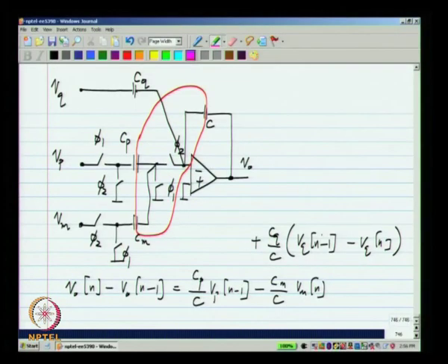Now, in this course we will not deal with the switch capacitor filters in such great detail. So, what I will do is show you a switch capacitor topology for a second order filter, which turns out to be slightly more efficient than transforming each integrator using bilinear transform. Transforming each integrator is certainly possible, but the topology I am going to show you happens to be more efficient, and it is a well known topology for generating all kinds of second order transfer functions.